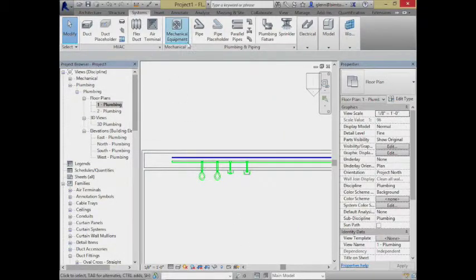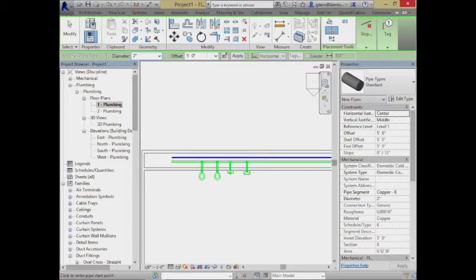Let me go ahead and even run a third pipe in there. I'll say pipe. It's going to be my domestic hot water pipe. Okay, and this is the feed pipe for the system. This one I could leave at 5 feet, but if I put the hot and the cold exactly at 5 feet, every time I'm trying to go towards the fixtures, I'm going to run into the other pipe. It just doesn't make a lot of sense to put them at exactly the same height. So I don't know, maybe this one's going to be at 4'11" or something like that, or maybe 4'10". Yeah, your plumber will appreciate it if you give them a little breathing room so that they don't have to be right on top of each other.